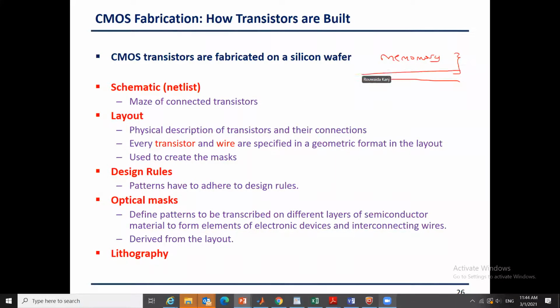Okay, and then I can draw on another processor, and I can draw what we call a through silicon via. So this is called a TSV, which connects metal layer to metal layer. Now there are vias that connect one chip to another chip so that they can stack the different functional chips. Of course, heating is a problem and stuff like that.